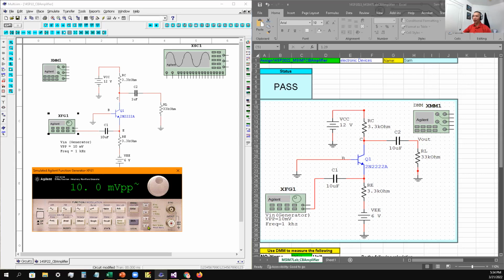Yeah, it gave me a flash right here. And so, like I said, I can move my cursor to a location where I can change it. Now I can turn this knob here to the right or left, so I can start changing. That's as small as it goes. So I can push 2 for 2 or change it back to 1. Now it stays at that 1. I don't press anything except the number that I want the value for. And then you can set up the frequency, which is 1 kilohertz.